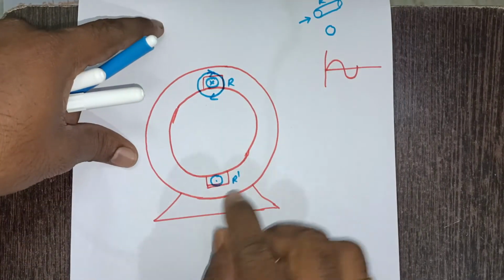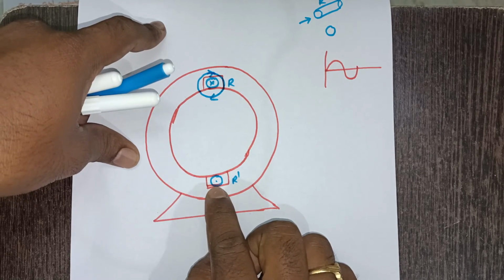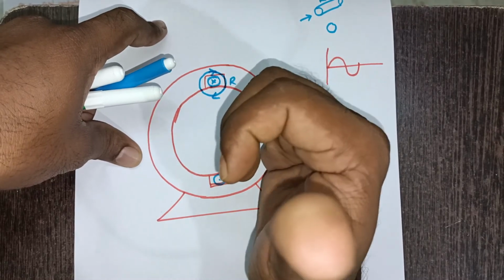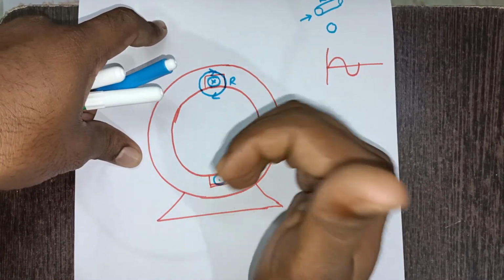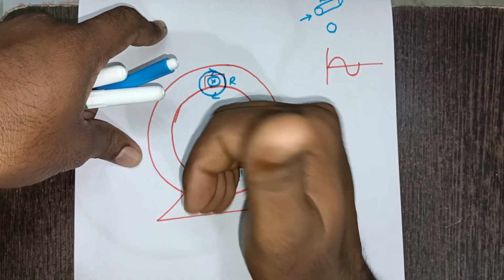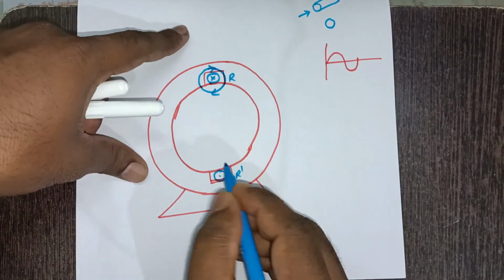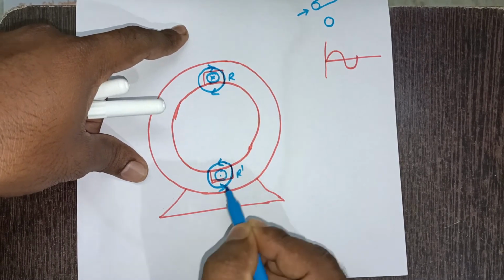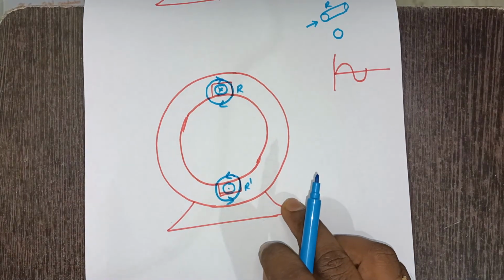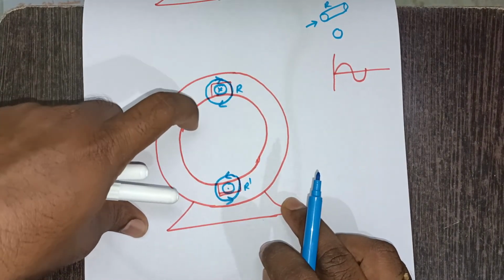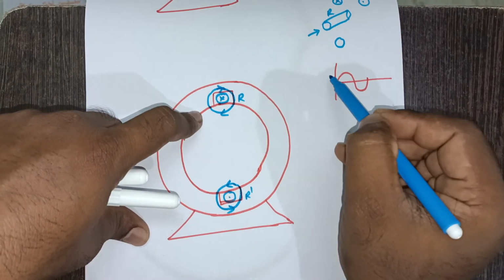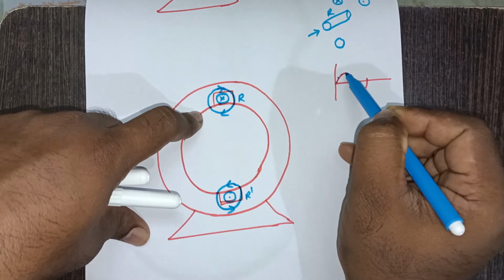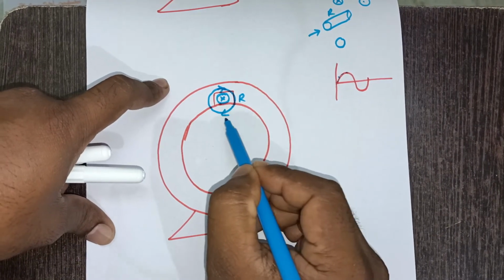And coming to lower side, see it is dot notation. Dot notation means current is coming towards us. So if you represent that current with the thumb direction, which is pointing towards us, and remaining forefinger curl represent flux around the conductor, which is there in anti-clockwise direction. So therefore, I can show here flux direction here is anti-clockwise like this, right? Now, this is how flux around the conductor is produced, right? So as current magnitude increases from 0 to towards some value or towards maximum value, what happens? Amount of flux lines around the conductor increases, right?